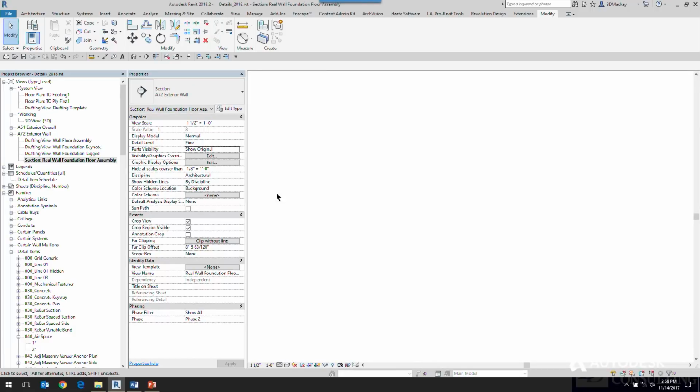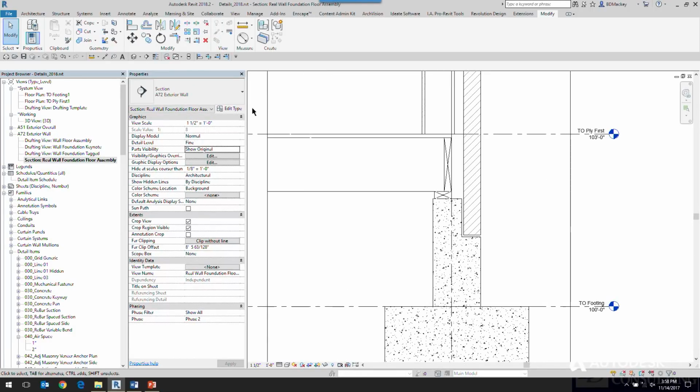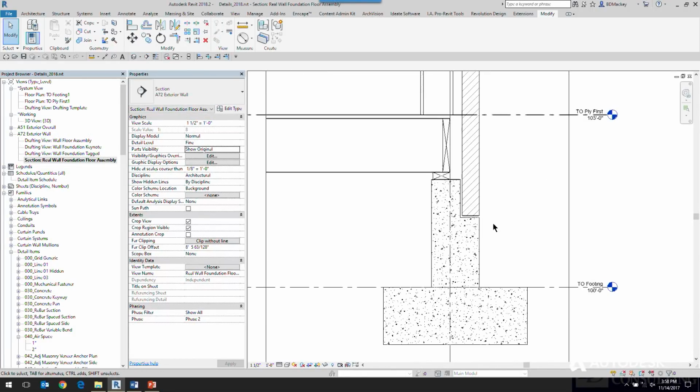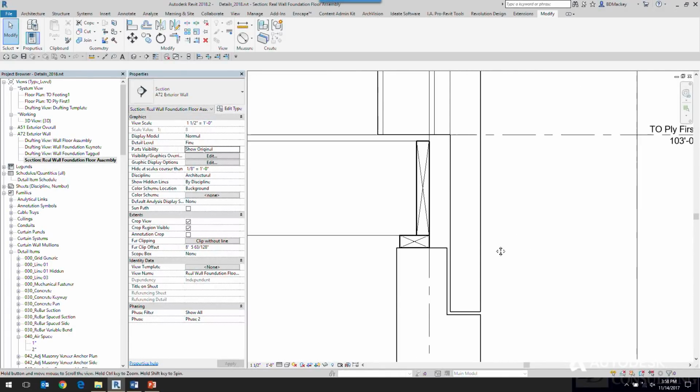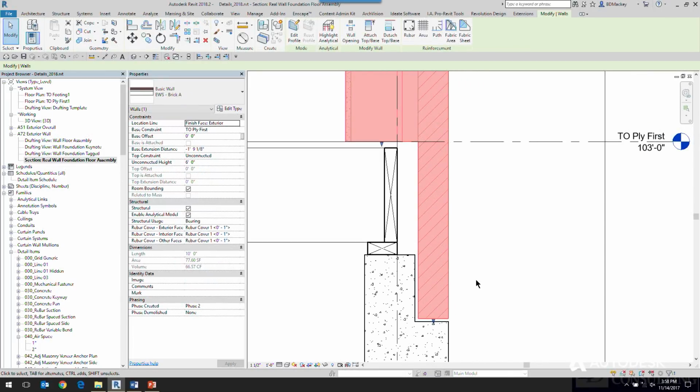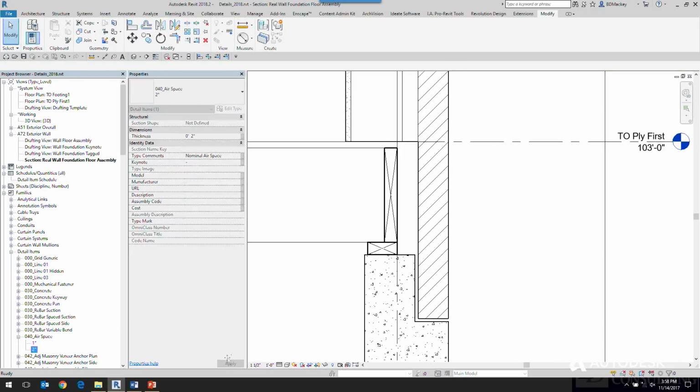So if I were to cut a section through that view, you can see that even in this view, I'm still going to have to come back and annotate over it. Right? So you can see, yeah, I even modeled my brick going down where it needed to be, but I can't get the sheathing and the air gap to stop independent of where the brick is. So this is where I would be saying, oh, gee, I know I'm going to have a 2-inch airspace.